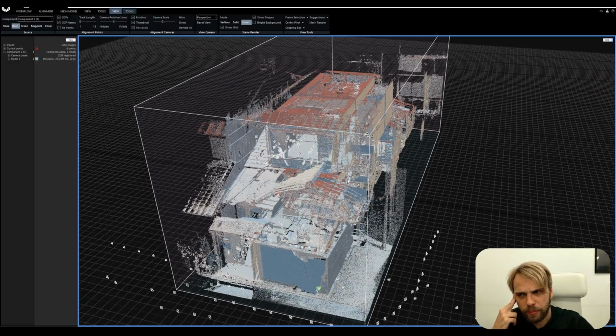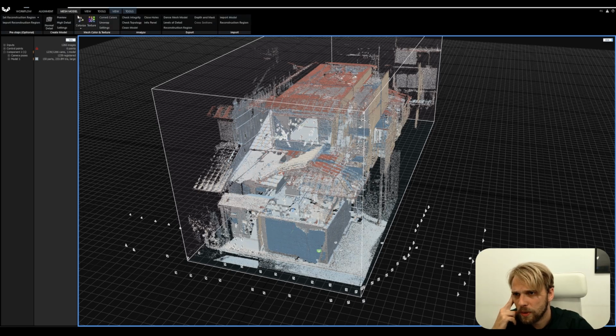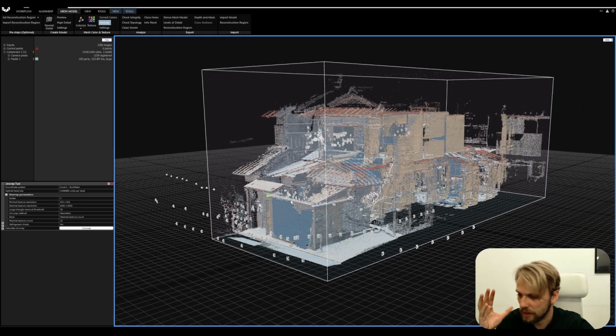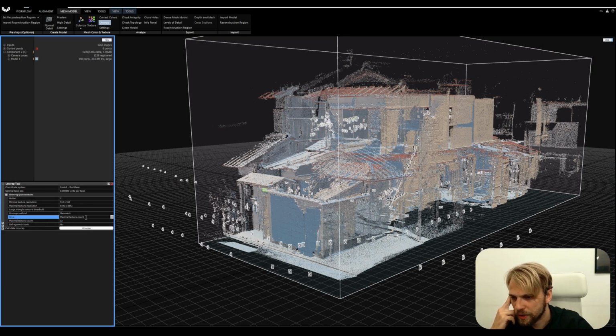Let's build the UV unwrap. The way I do it is I go to mesh model, unwrap. I would choose, first of all, how many texture tiles I want for this whole geometry to be unwrapped, with a certain texture of the model. I always choose maximal texture count because then I can put down how many 8K textures I want.